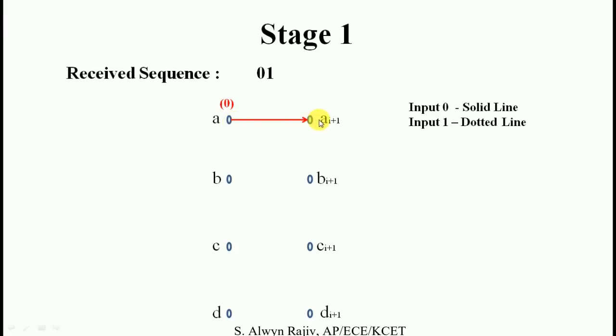This time, the code word becomes 0, 0. Now we are going to calculate the metric value. This metric value is found with the help of the Hamming distance. Now we compare these two values, 0, 1 and 0, 0. How many bits are changed? Only one bit, only the LSB.